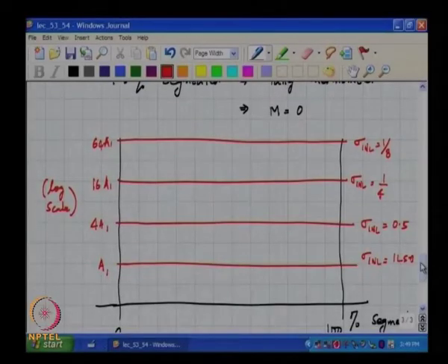So, for a given sigma DNL, if I had some area needed for a fully thermometer decoded DAC, right. Can you comment on what will happen when I go fully binary?